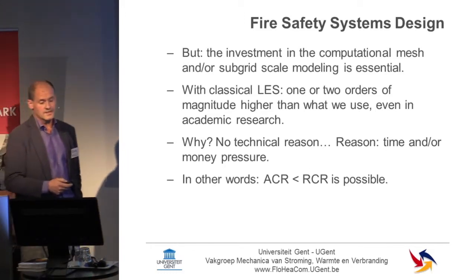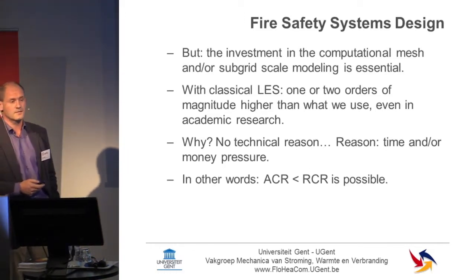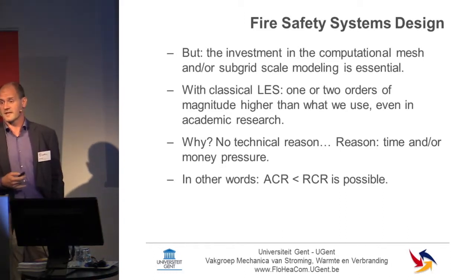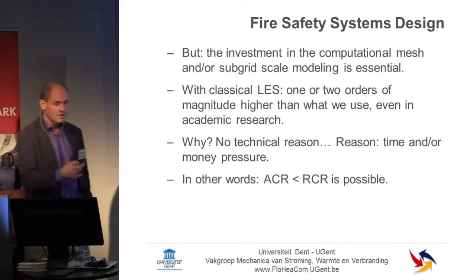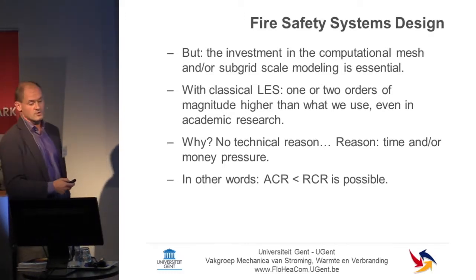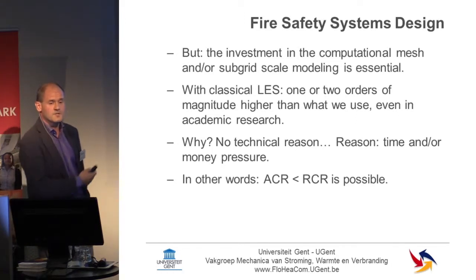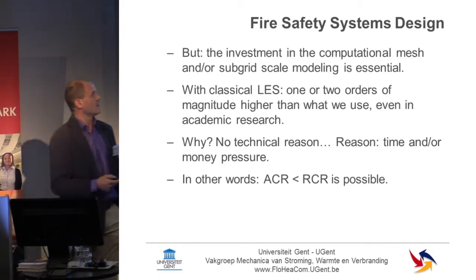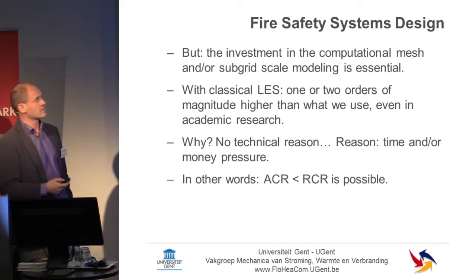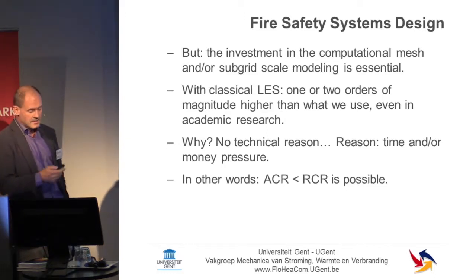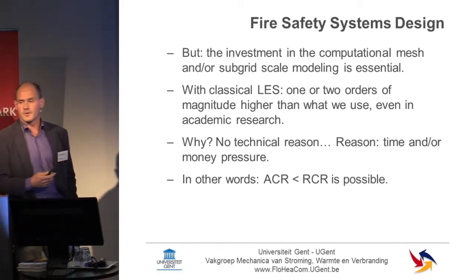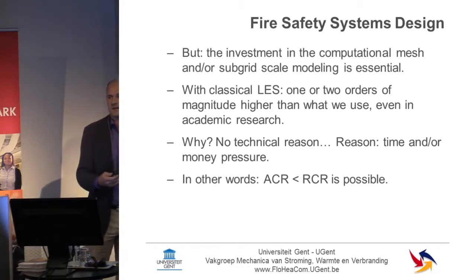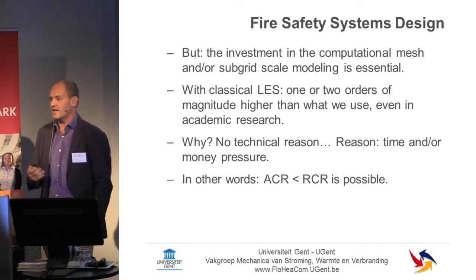But, and the but is very important in this good news story, we've been very cautious in determining our computational mesh. We have taken our time that we don't always have, and we also invested in computer power in order to be able to do this. Because we did this calculation with FDS, Fire Dynamic Simulator, I'm sure you know it. This is a package that was developed at NIST in the US. Why am I saying this? Because turbulence in this computation package is calculated based on LES.